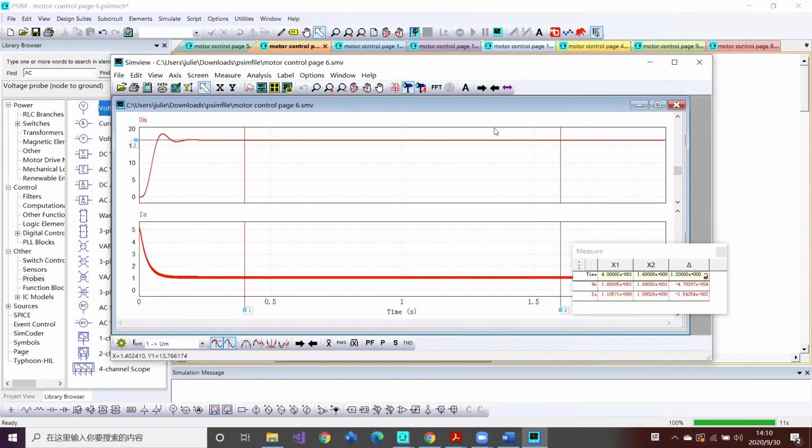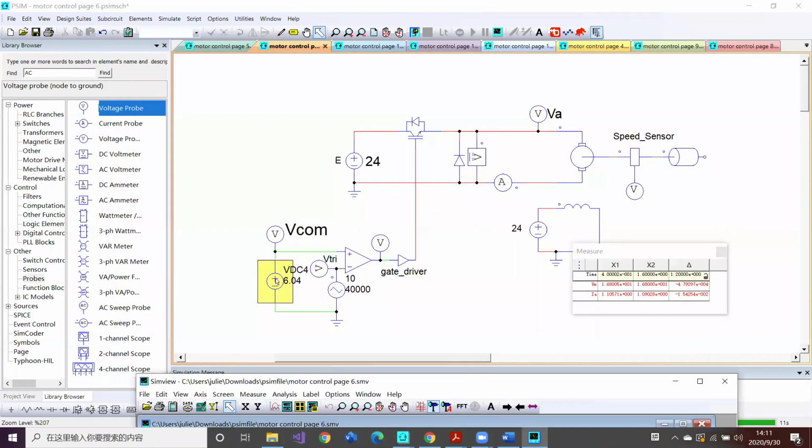16.8 volts. So you might have questioned that we designed our buck converter, and by the calculation, it should give us 14.5 volts. But actually what we measured is 16.8 volts, right?